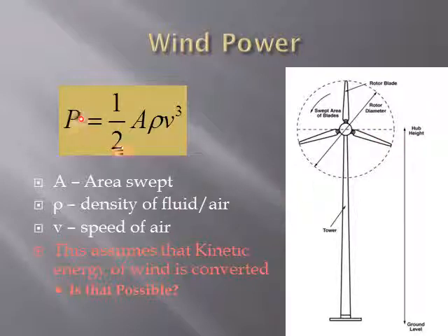So whenever you're calculating power done by a windmill, you have to take the initial amount and subtract from it 1/2 rho v cubed afterwards. So it's the energy before, and afterwards the same expression with the velocity afterwards. Keep in mind, if the air is slowing down, it will actually become more dense, because more molecules come through and pack up together, like a traffic jam. As it slows down, the cars get closer together. So you'll have rho before and velocity before, and you subtract the density, rho, afterwards and the velocity afterwards, and that would be the total actual power.